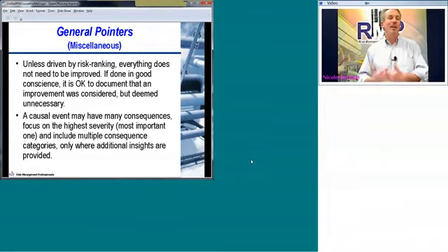If the team has really thought about it and identified that it's okay as is, and then you document in the comments column that something really wasn't necessary, that means you can stop a lot of people from having to spend time rethinking it over and over and over again outside the HAZOP study, and they can be thinking about more important things in terms of design and operations improvements that really do have a nice impact on safety.